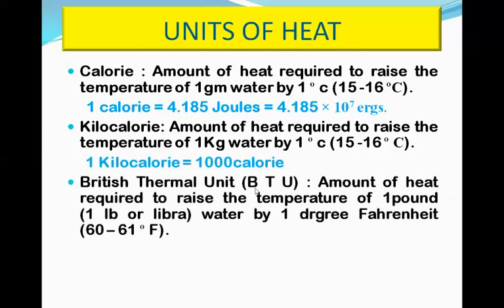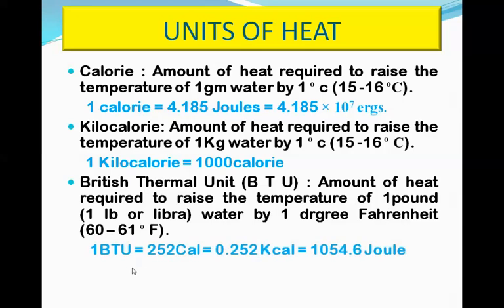Then British thermal unit, or BTU, is the amount of heat required to raise the temperature of 1 pound, that is 1 lb or libra, of water by 1 degree Fahrenheit, from 60 to 61 degrees Fahrenheit. The relationship between BTU, calorie and joules is: 1 BTU is equal to 252 calories, 0.252 kilocalories, 1054.6 joules, and 1 kilocalorie is 3.968 BTU.